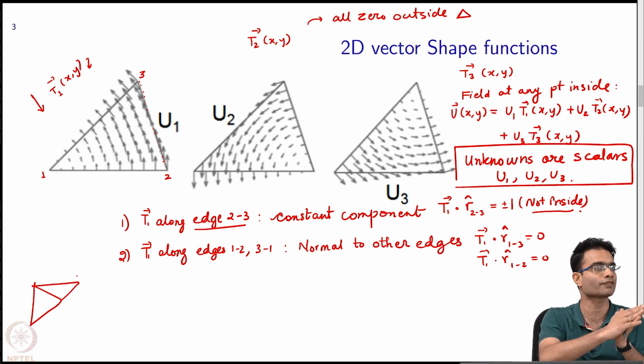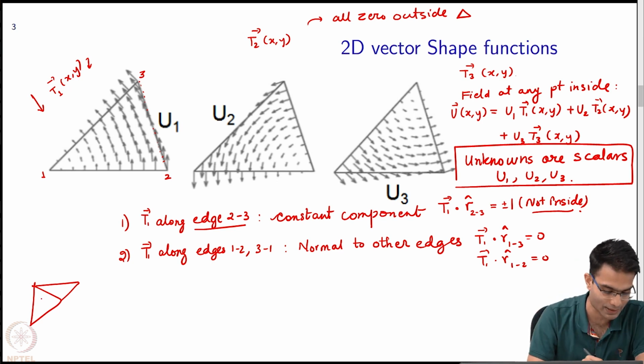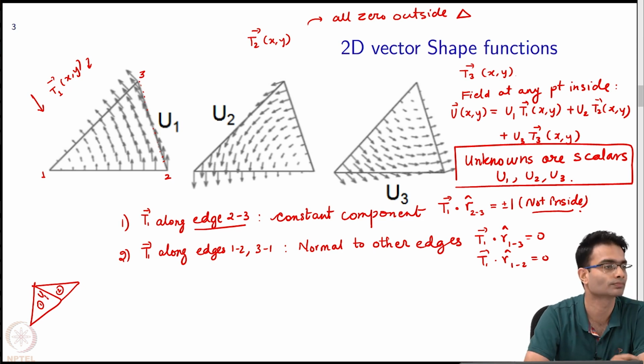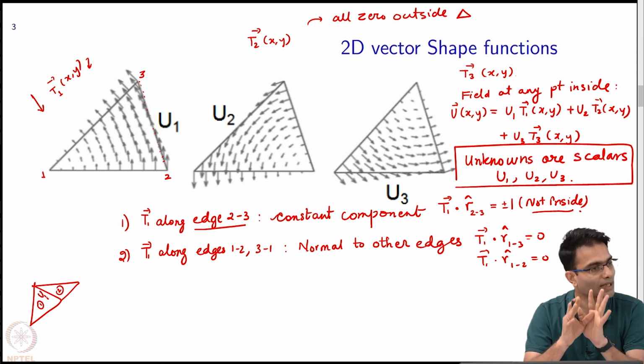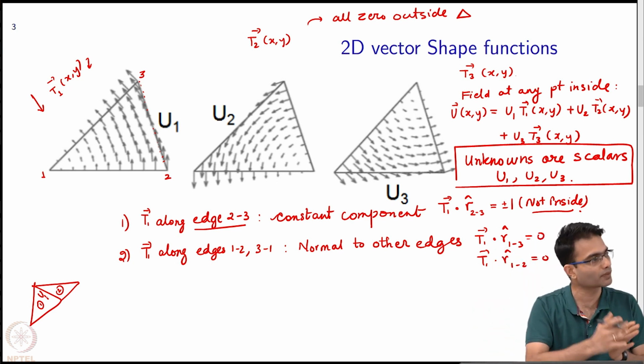At any boundary interface, tangential fields are satisfied. So, if I take the basis functions inside element 1 and element 2, along this edge, if I assign the variable to be u1, then that u1 is common for element 1 and element 2, because that value u1 is shared.